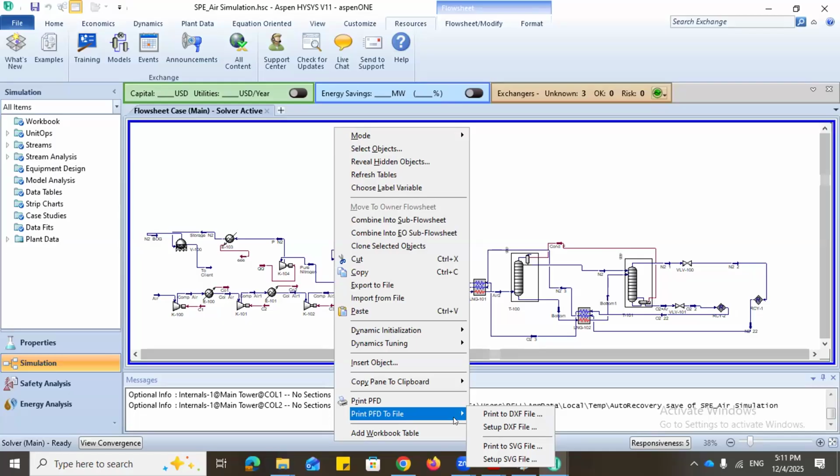But that doesn't mean that process engineers don't use AutoCAD. We use AutoCAD in P&ID drafting if you want to develop your P&ID. There's a difference between P&ID design and P&ID drafting. Take note. P&ID drafting is when you are using AutoCAD to draw those things. P&ID design is when you are sizing all those PSVs, control valves, gate valves, check valves, doing the necessary sizing and designing aspects. So take note, there's a difference between drafting and design.